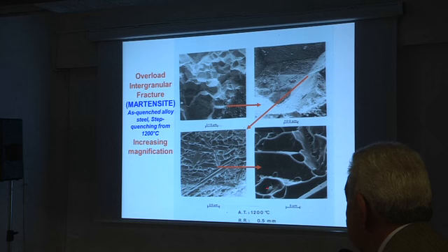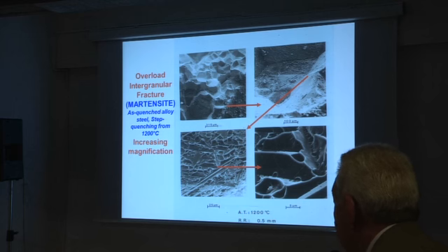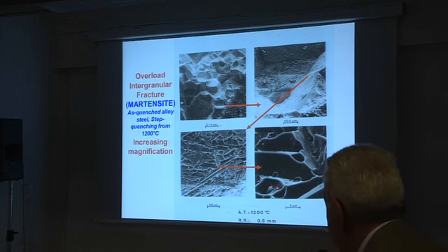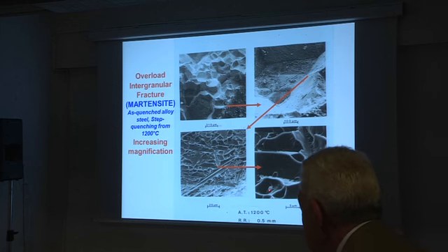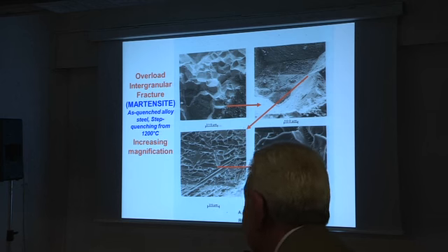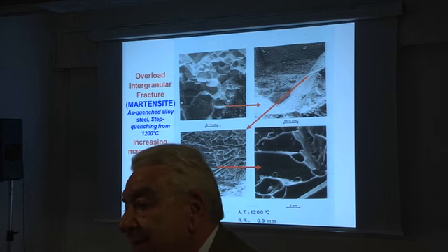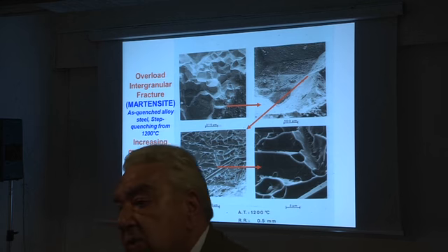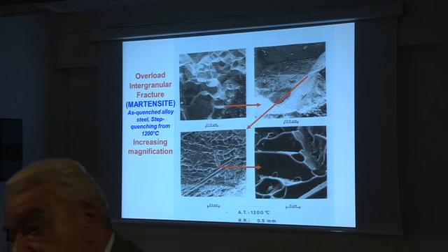And you can see here a small void, a microvoid, that formed by decohesion from a previous second phase particle, a non-metallic particle. Why do you see it is a non-metallic particle? Because you see that it is much more glowing, because it absorbs electrons and does not conduct them to the bulk of the material.